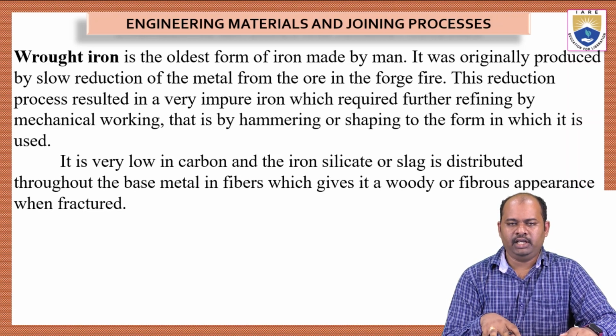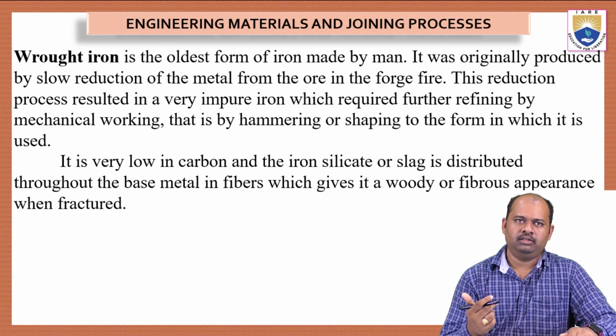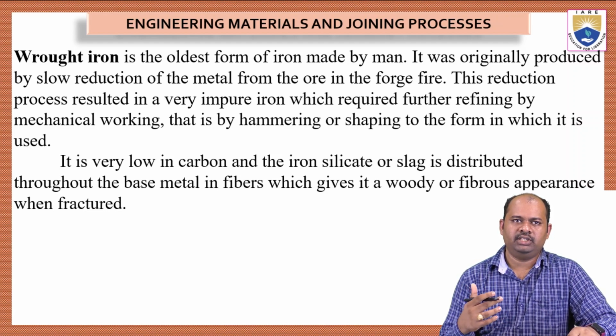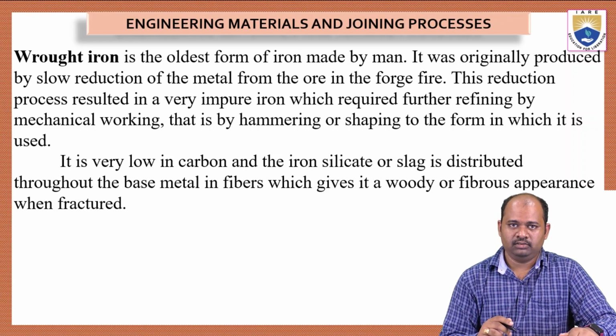This entire thing is done by forging the iron and hammering it by hand. It is very low in carbon, and iron silicate or slag is distributed throughout the base metal, which gives it a woody or fibrous appearance when fractured.